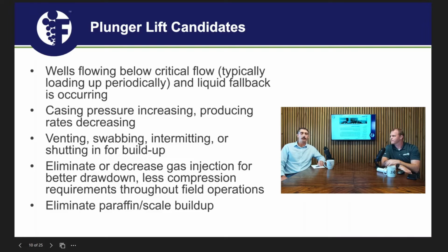One of the biggest problems typically when we put on a plunger system with a group that's maybe not as educated or experienced with it is that people get very concerned with strictly the arrival of a plunger. Hey, my plunger's running every time. But if we're not paying attention to those times, we could be either breaking equipment or prematurely wearing it out.